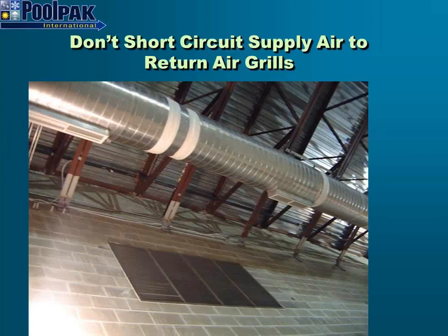Just some standard air distribution considerations. Make sure that we're not short-circuiting the air right to the return grill. And make sure you wash the windows and the doors and the walls with dry supply air. Don't return air through the locker room. This sort of thing can happen.